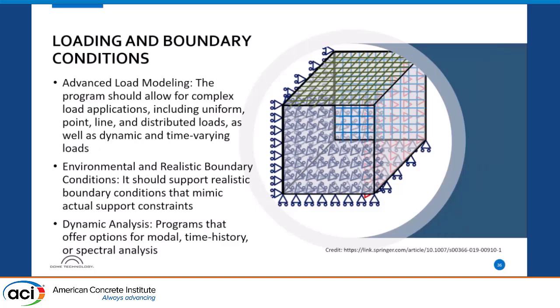You can kind of look at what kind of different boundary conditions do I need? How complex do I need them to be? Do I need springs on certain areas? Do I need fixed, or am I okay with pinned? And so you want to be able to take into account all sorts of loads that you can put on there,